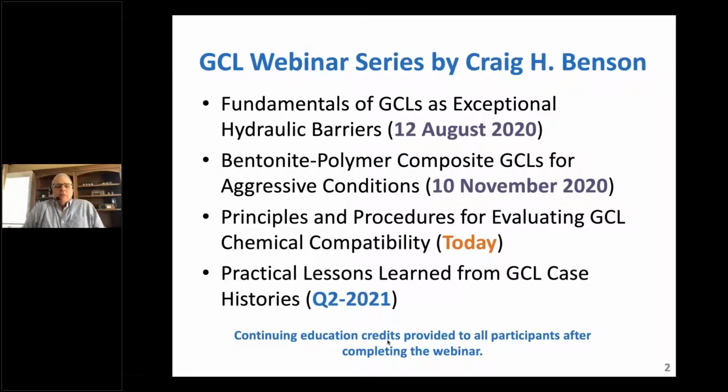So just a little recap on where we're at. This is a 4-part series that we dreamed up last year. It's been a lot of fun. This is the third part. The first part was just fundamentals of GCLs as hydraulic barriers. The second webinar was on bentonite-polymer composite GCLs, some of the newer products available for about the last 10 years, with a blend of sodium bentonite and different types of polymers that are intended for more aggressive conditions. Today, we'll be talking about chemical compatibility testing.